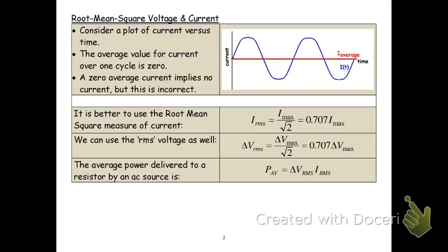Okay, so then we can talk about phases, or we can talk about the actual wave. But here's a problem we have with alternating, and that is the fact that when I average alternating, I always get zero. And I'm looking at current here. So imagine the situation where I have 1,000 amps oscillating through. What does that mean? 1,000 amps flows that way, and then flows that way, and then flows that way, and then flows that way. So the electron doesn't make it from my battery to the light. It would in DC.